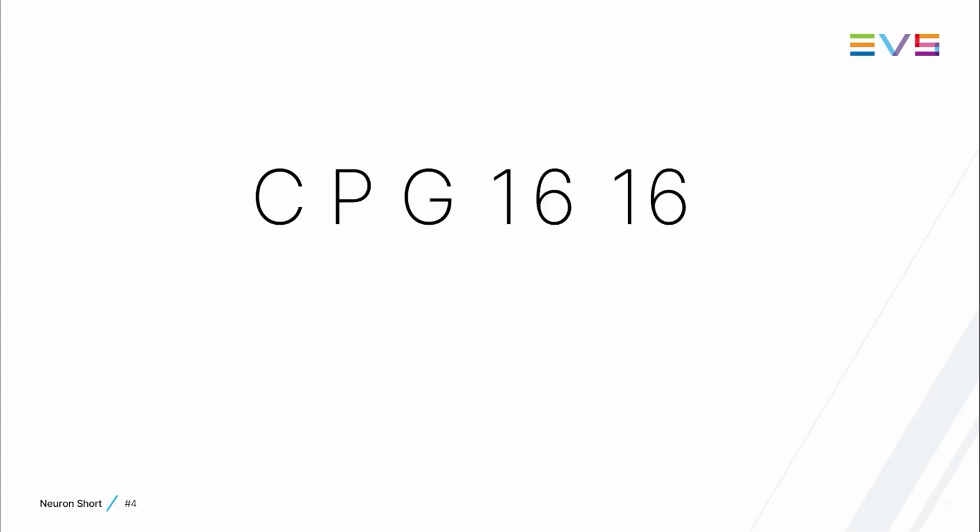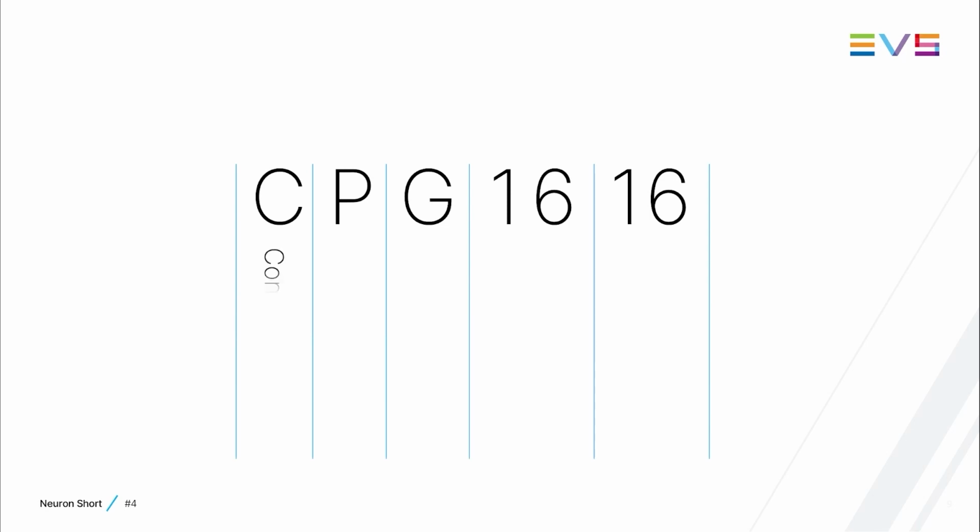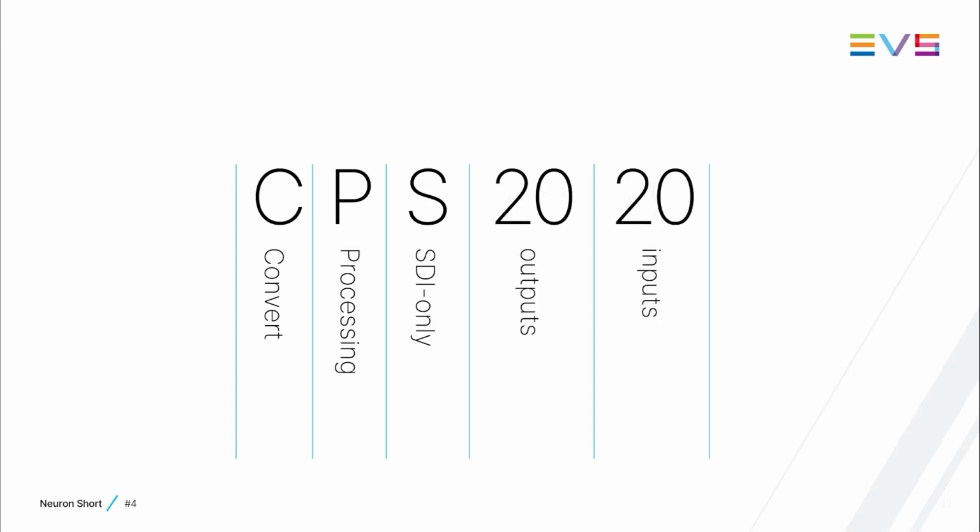Neuron convert cards appear in Cerebrum as CPG, CPI or CPS, followed by 4 digits, where the CPG stands for Convert Processing Gateway, CPI stands for Convert Processing IP Only, and CPS stands for Convert Processing SDI Only. The 4 numbers behind the 3 letters indicate the amount of outputs and inputs again, just as with the bridge cards.